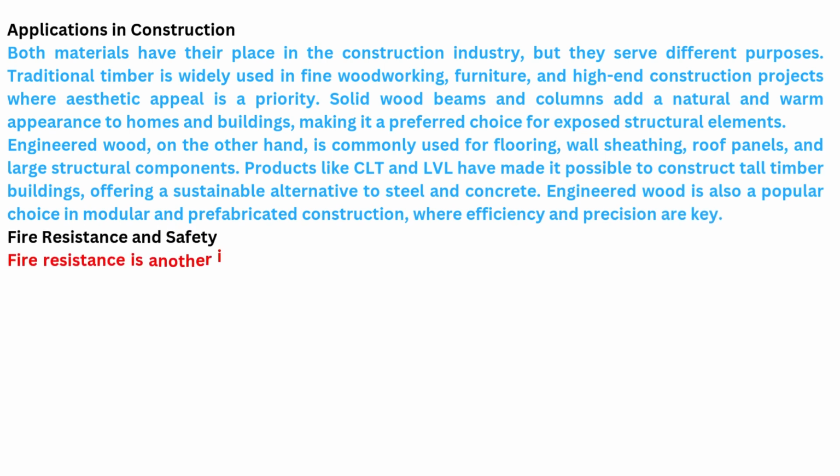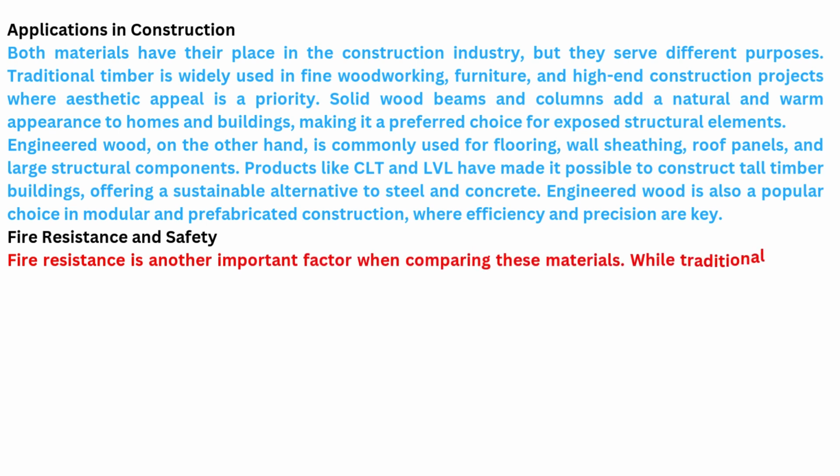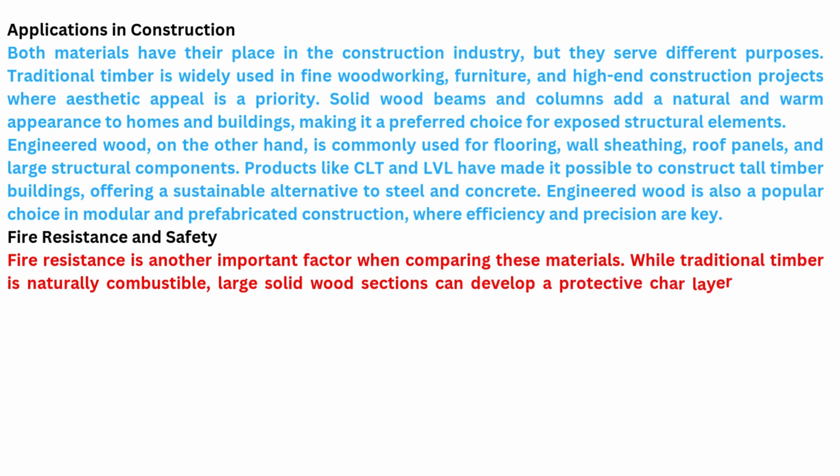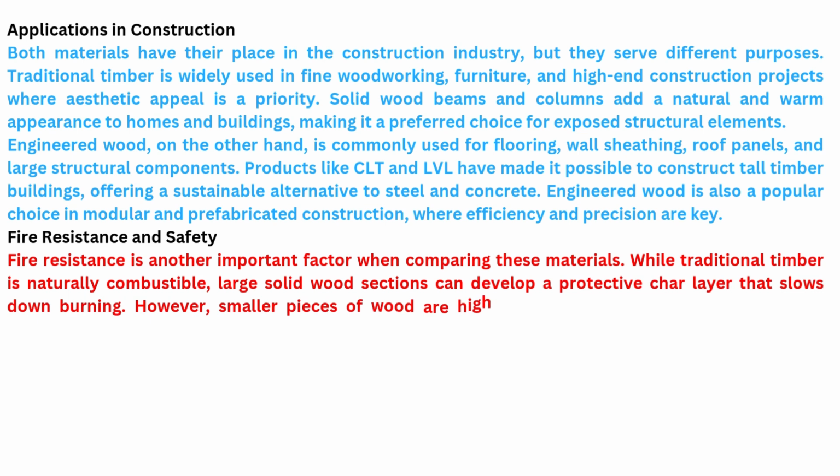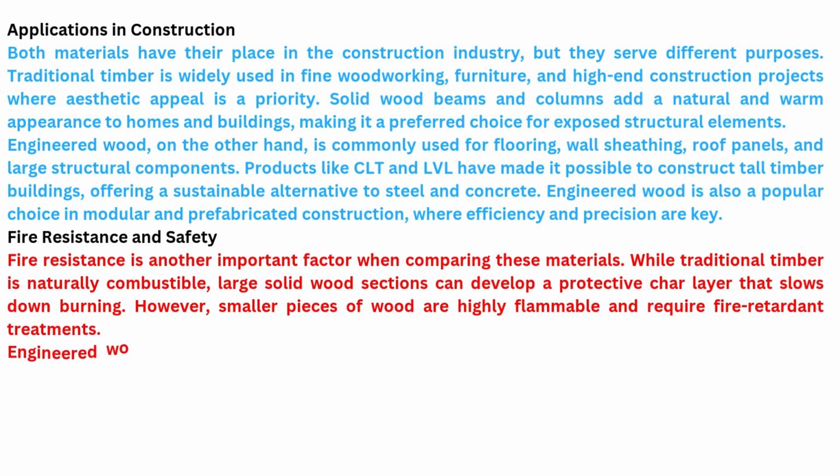Fire resistance and safety. Fire resistance is another important factor when comparing these materials. While traditional timber is naturally combustible, large solid wood sections can develop a protective char layer that slows down burning. However, smaller pieces of wood are highly flammable and require fire retardant treatments.